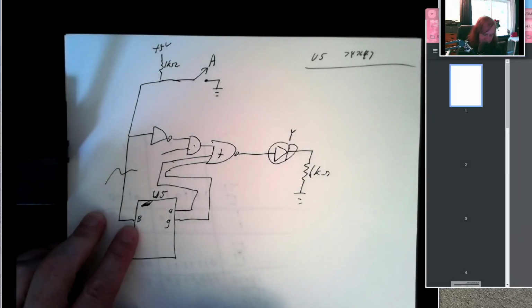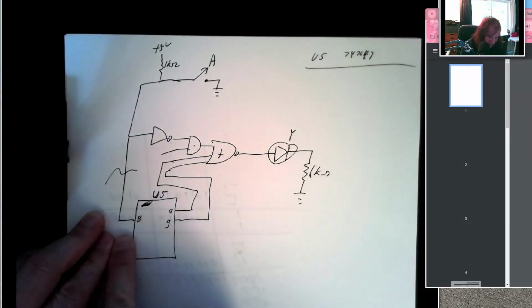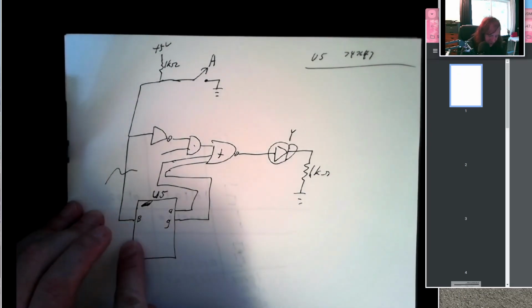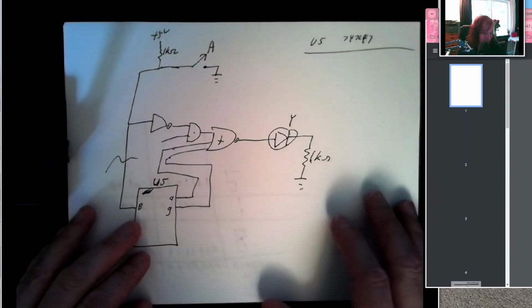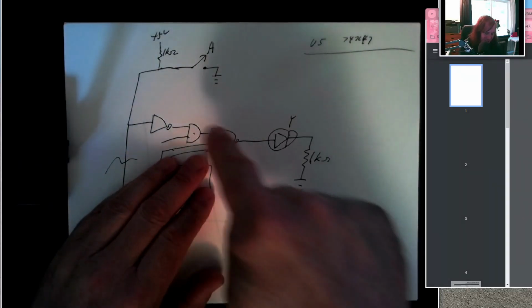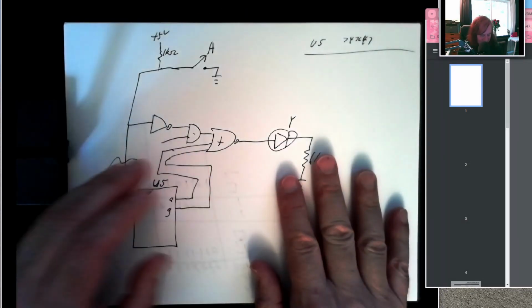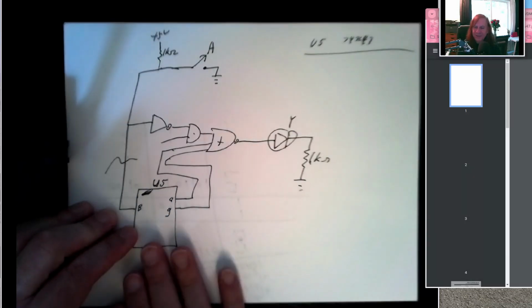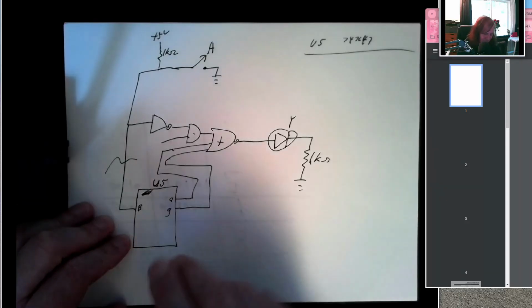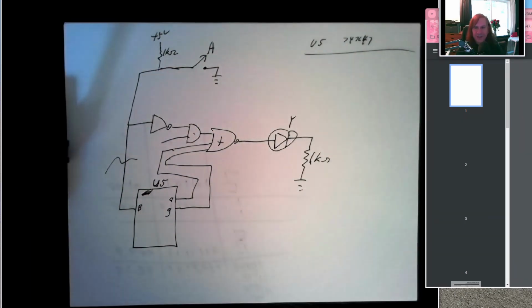And if output G happens to be over here, I can put it on this side of the rectangle so it comes out there. There's no need to bring my wire around over to here, right? So we want to make these things easy to read, and we want them to convey information about the behavior of the circuit. So for logic gates, switches, LEDs, resistors, ground, power, we use the standard symbols. But for these more complex blocks like the 7447 or the priority encoder or a half adder or a full adder, we can just draw a rectangle and label the inputs and outputs based on the function that they're performing.